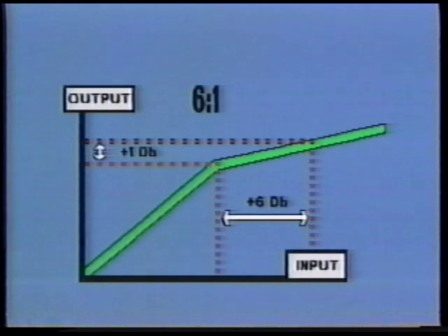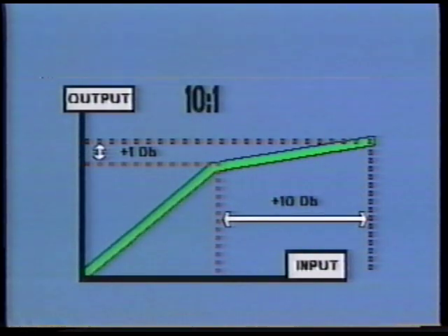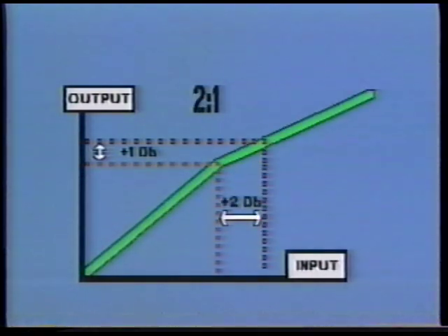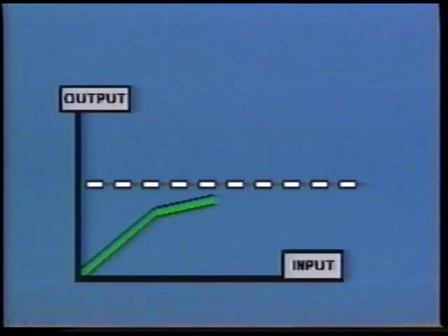The ratio determines the amount of gain reduction that will occur when a signal passes the threshold. Limiters and noise gates have a very severe ratio that reduces the signal's gain nearly completely, while compressors and expanders have more gentle ratios. The range of a VGA defines the outer limits of its effectiveness, and on some expanders and gates, this limit is adjustable.